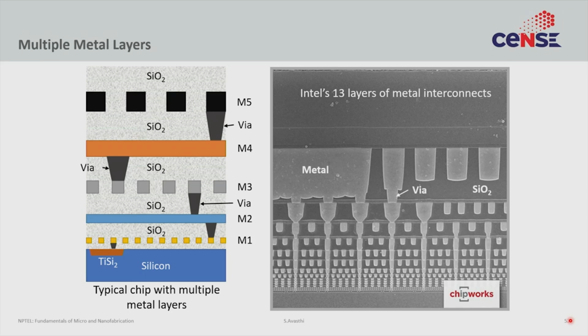So, till now we have looked at various ways in which physical vapor deposition is done. Specifically, we looked at evaporation, sputtering, and in much lesser detail, pulsed laser deposition. Now, what we are discussing is how the deposition of metal affects the properties of the devices. So, this sort of lecture would go into details such as electromigration, how do we deposit multiple layers of metals, and how the properties of each deposition method affect the properties of the metal and then affect the properties of the device.